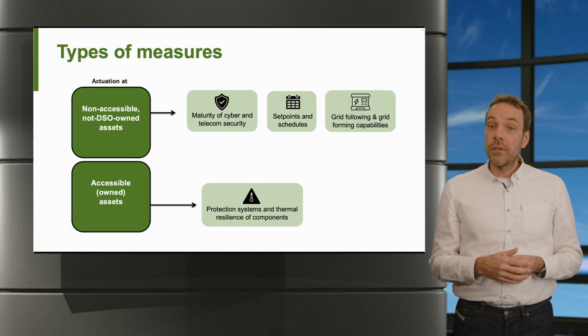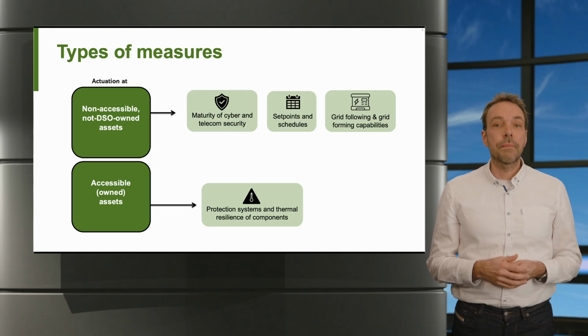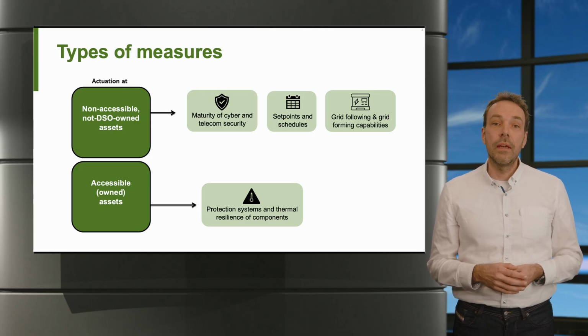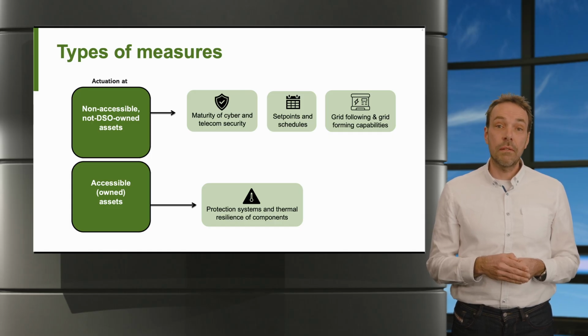For DSO-owned assets, we use protection systems and also the thermal resistance of components. Cables and switches are designed for worst-case conditions, which sometimes means we can safely use additional capacity, for example, during colder periods. This enables us to avoid using high-impact security measures if not necessarily needed.